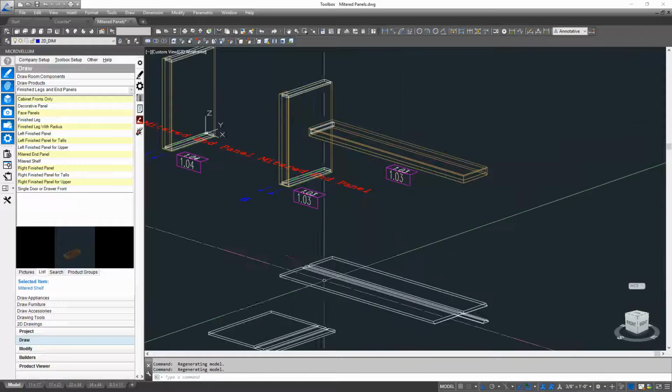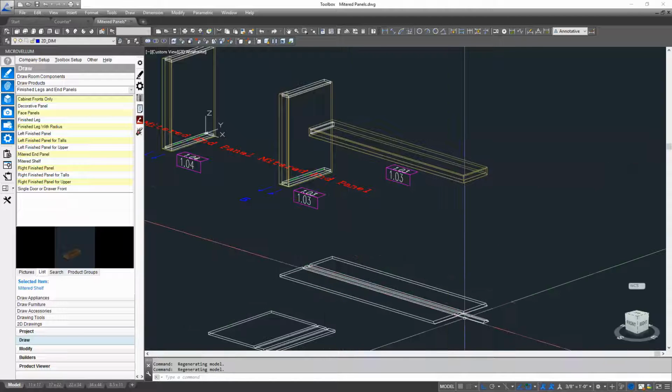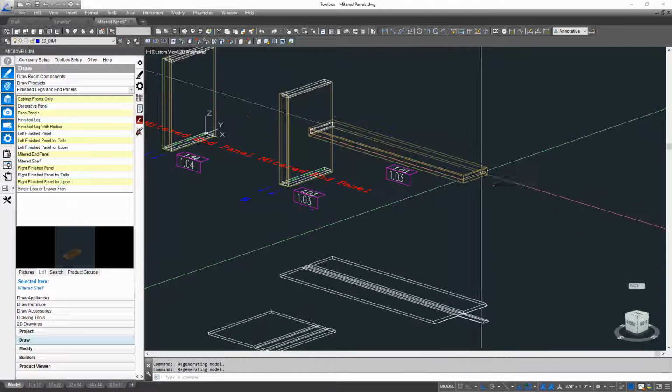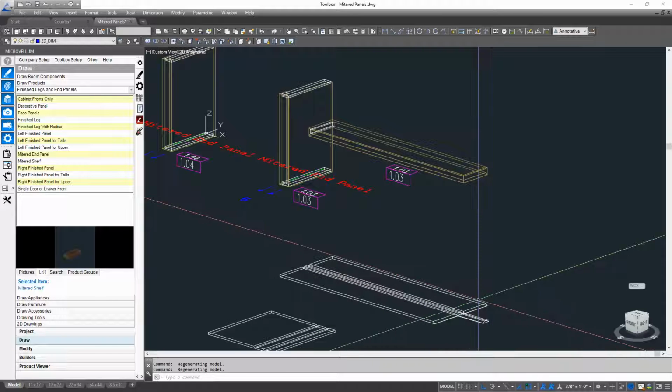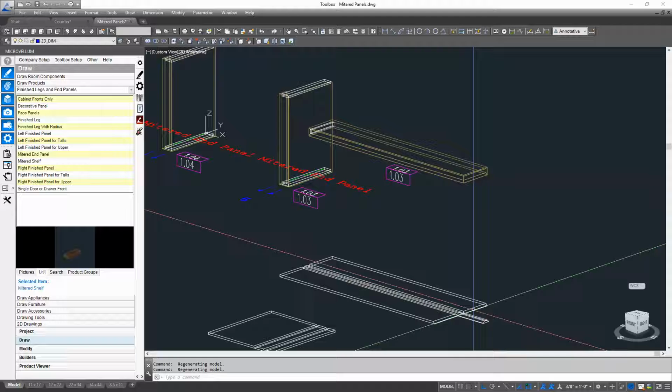And you can see that here's the miter fold blank. I turned on the miter fold for that, and you can see that the blank is becoming quite complex when we have to fold those parts back together. Depending on how the grain direction settings are set, it will adjust that miter fold blank accordingly. And so right now I have the grain direction running horizontally all the way around, and so it's creating that piece off the end. If I change the end grain direction to be vertical, then it would add that piece on to the end of the blank there.